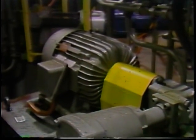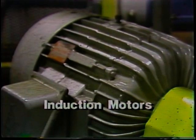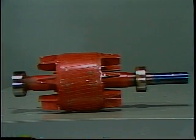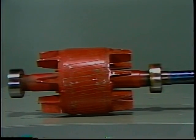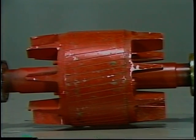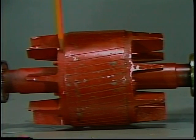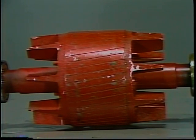In induction motors, the rotor poles are the result of currents induced in rotor conductors. Look at the rotor closely. Often, all you'll see is a round core of laminated steel. But notice the aluminum rings on both ends. They are not there just to hold the fan blades, which are usually cast as part of the rings.